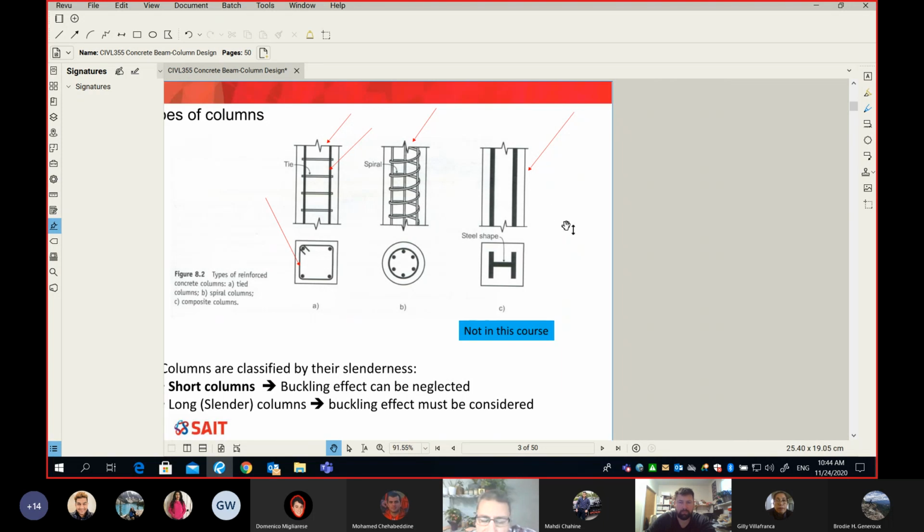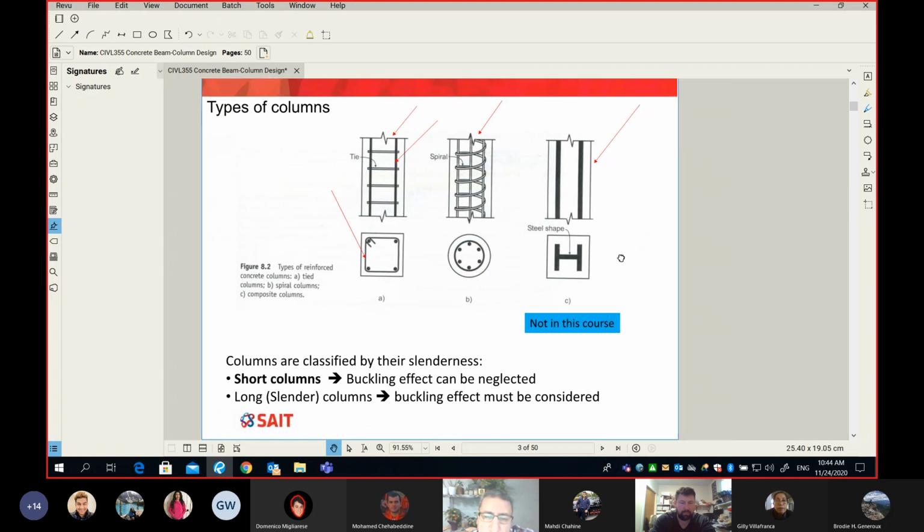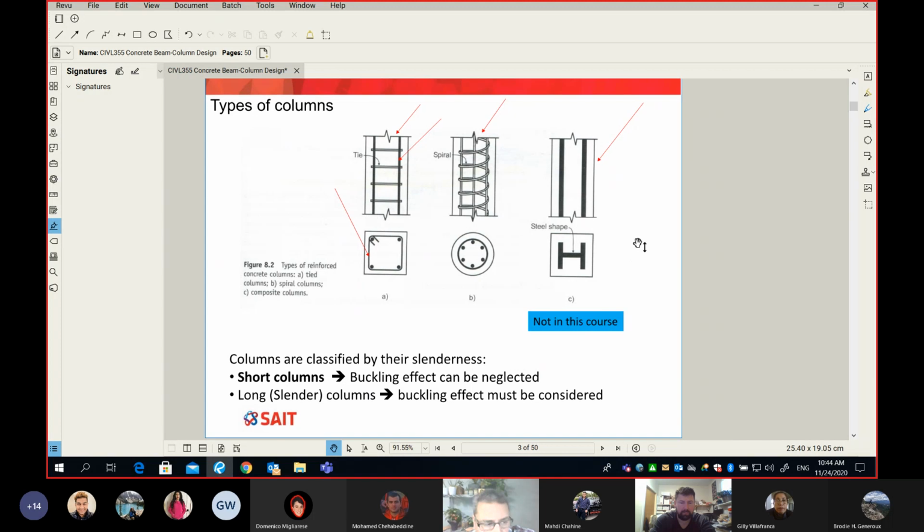In the past, people used concrete to make high-rise buildings, but concrete is not as strong as steel. So what happened is they decided to go for steel because simply the bigger your section, that's a problem, huh? If you end up in the basement with a column that's 1 meter by 1 meter, that's a serious problem because simply you are eating up the usable area in your floor plan. So to get more floor plan, people started to use steel.